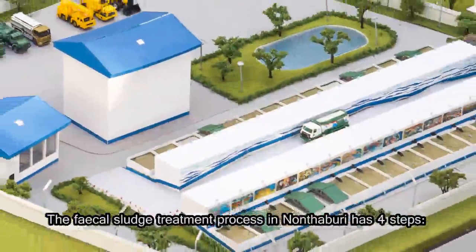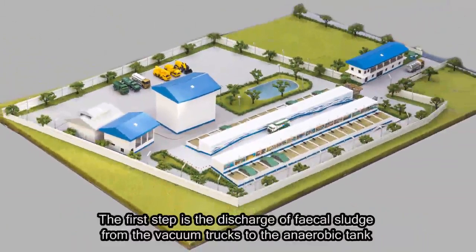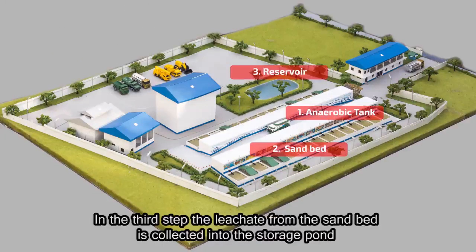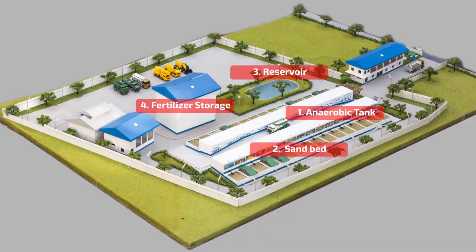The fecal sludge treatment process in Nonthaburi has 4 steps. The first step is the discharge of fecal sludge from the vacuum trucks to the anaerobic tank. The second step is to pass the fecal sludge to the sand bed. In the third step, the leachate from the sand bed is collected into the storage pond. In the fourth step, the dried sludge from the sand bed is scraped for fertilizer purpose.